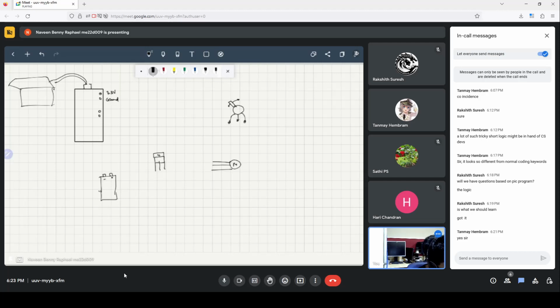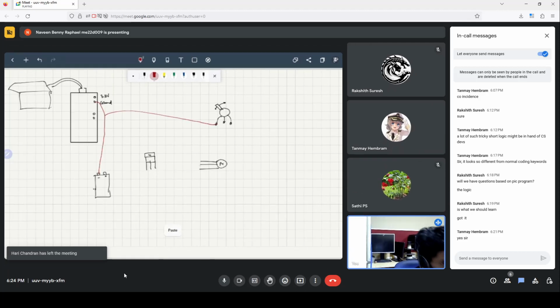So, time for colors. So I first connected. We obviously had a breadboard also, but I'm not going to draw the breadboard because that's a little absurd. We first connected the ground, all the grounds. The potentiometer has a ground, and this one. The motor also has a ground, which is the middle pin, and the voltage regulator had a ground in the middle pin also, if I remember correctly.